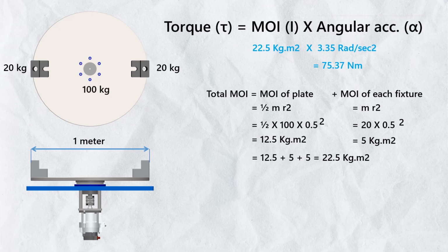So this is how we size a servo motor, and this is quite different from sizing an induction motor. With a servo motor, we do not really have to worry about the acceleration time in the same way. The reason is simple. The servo motor working principle is different from an induction motor. The servo motor is designed for precise control. However, it doesn't mean that we can just decrease the acceleration as much as we want to rotate any heavy system with a large moment of inertia.